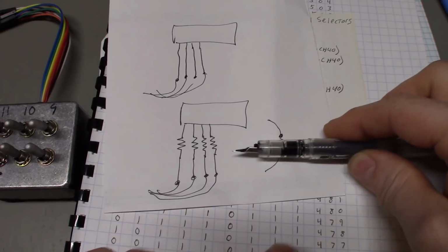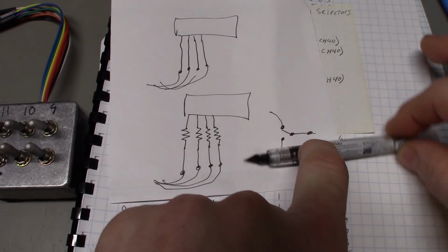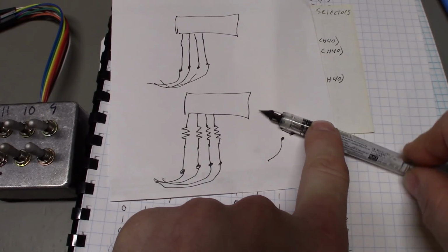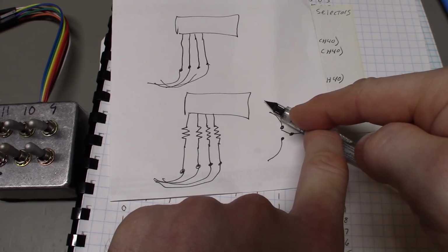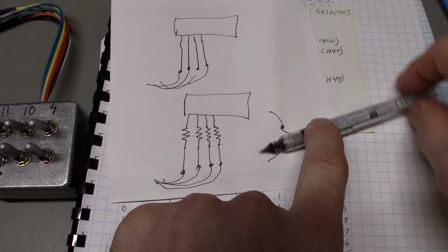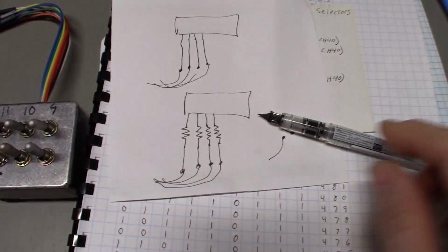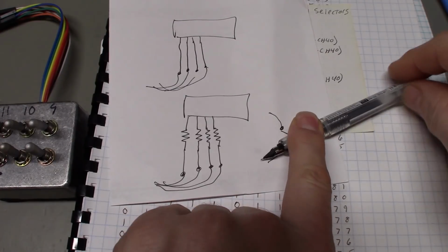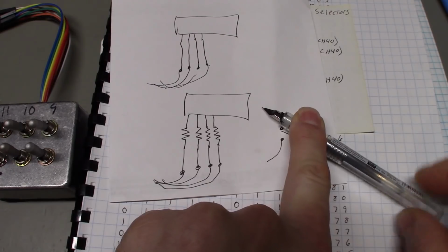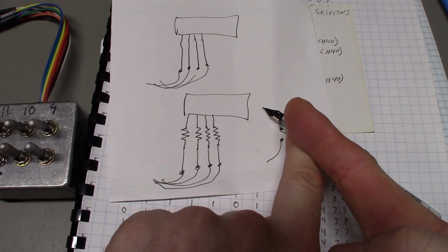When you flip the switch, that's another thing to remember with toggle switches: when you physically grab it, it's a pivot. So when you grab a toggle switch arm and push it down, the actual arm inside the toggle switch is going up. It's going the opposite direction because it's on a pivot. Just something to remember. So when you put your switches in, to keep them in the proper orientation: when you push a switch up, the arm inside is going to the bottom contact. When you flip a toggle switch arm down, the contact inside the switch is actually going to the top contact.